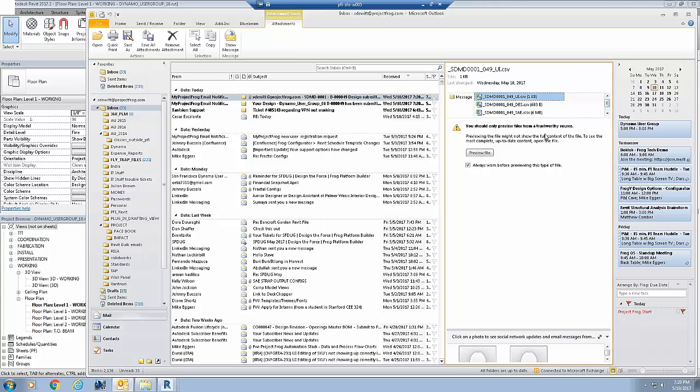There's the UI file, which kind of defines the building footprint. And then because I know what window we chose, right? We chose the opening that was offset, 7 feet off the ground, and it was a full panel opening. Well, because I know that window, I also happen to know the location of the window because we placed it in a slot, right? And then because I know what window I chose, that also tells me what panel I should be using, right? So in some cases, if it's a custom opening, it's just the opening size that is going to adjust, right? So we built some parametric wall panel families that basically automatically adjust to the different sizes of the openings that any one user can define.